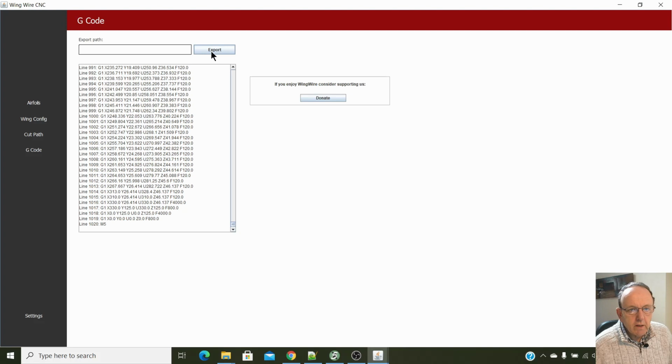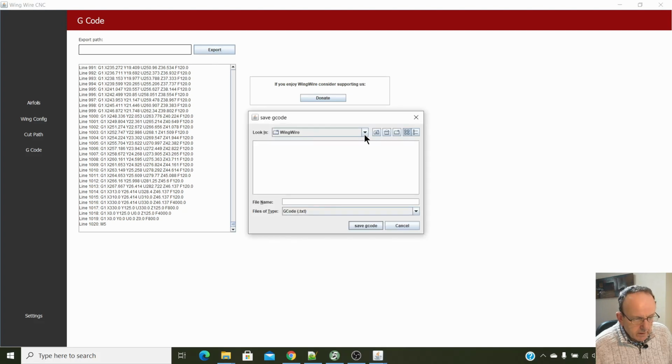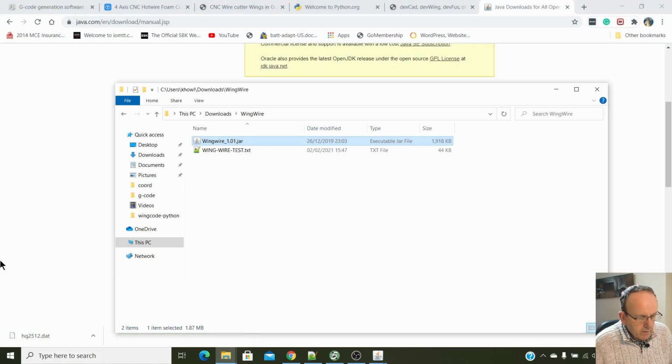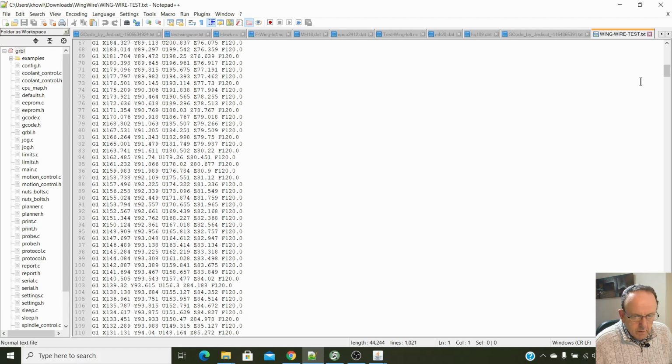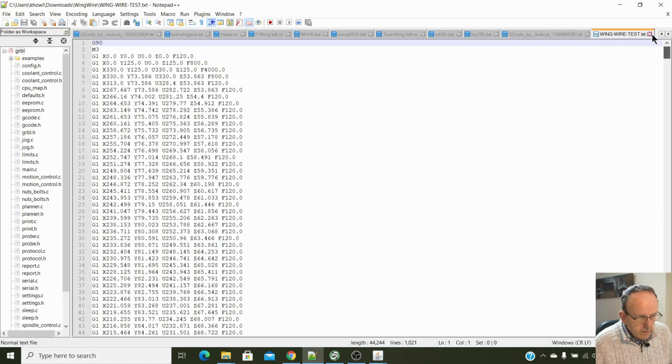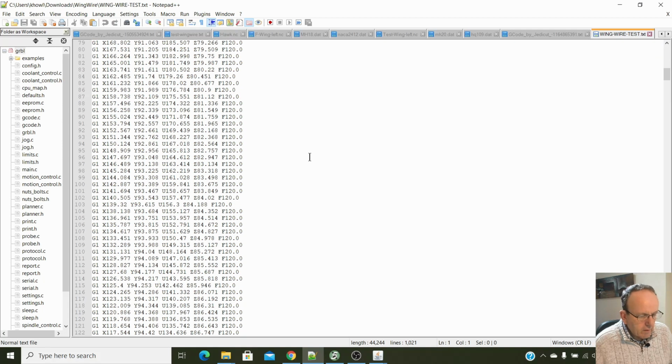So what we do now is we do an export, and yeah, we'll leave it in there, just so easy to find. Anyone can give it a name. We'll just call it wing wire test. There we go. So we've got wing wire test there. So here's our Gcode. So he's got a feed on every line, but you probably don't actually need that on every line. Thing with CNC, what it does, if you don't put a feed on the next line, it keeps using the previous feed until it changes.